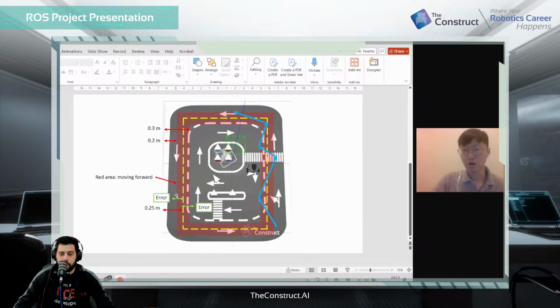The rationale behind this error calculation, instead of just calculating the robot's current position against the edge of the wanted area, is that I would like to have a relatively large enough value once the robot has exited the region, instead of just a small error, because a controller tends to minimize the error. If I only minimize the small error here, the robot will tend to always stay at the edge of the area. So I used the center line for calculating the error.